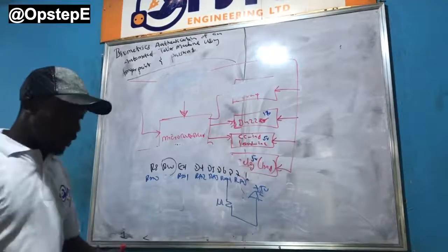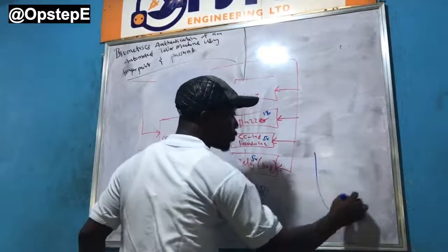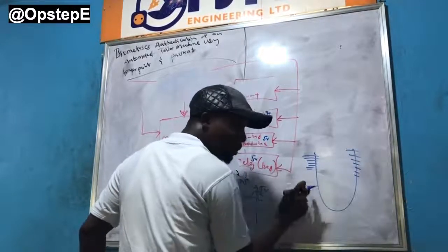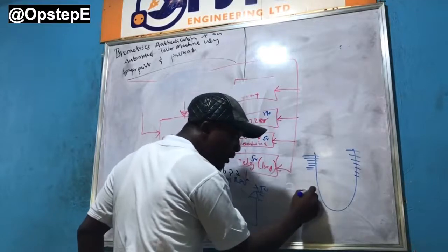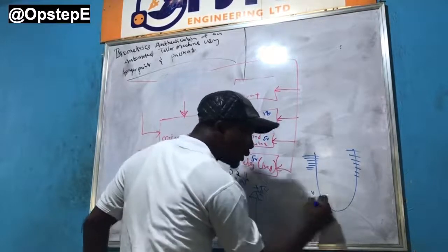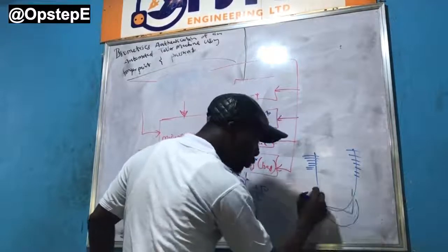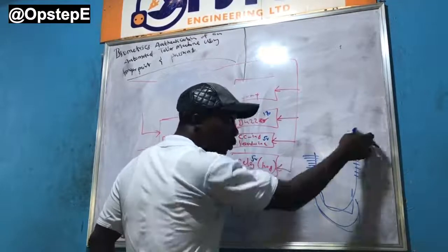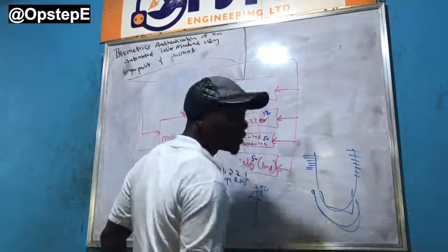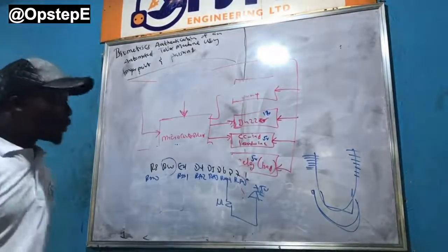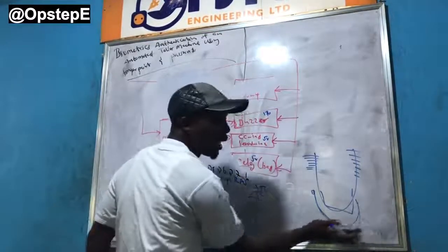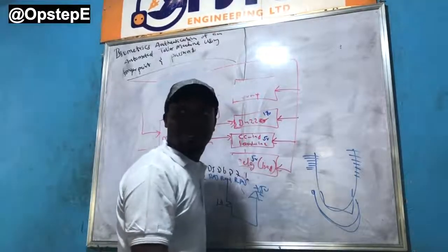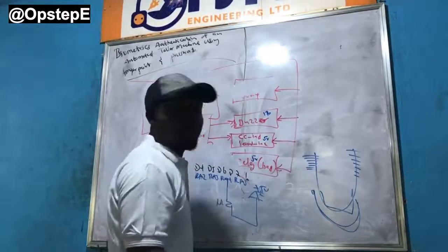They are not. If you pick up the microcontroller, your port A is here, your port B is here, and your port C begins from around pin 13, either 12 or 13, and goes down like this. So your port C is around this end. Your A is here, your B is here, but your C is from here down to this place. Do you get it? So if I use part of A here, I have to bring in another block here to take advantage of port C, and the PCB will be rough.